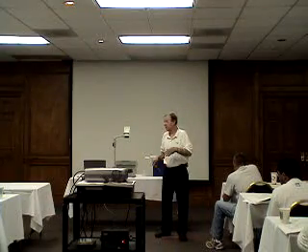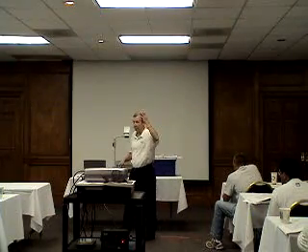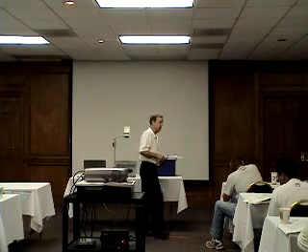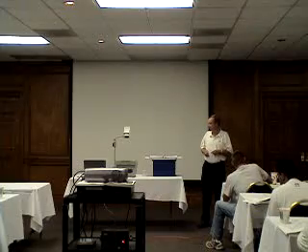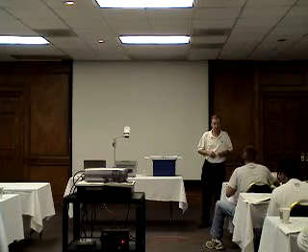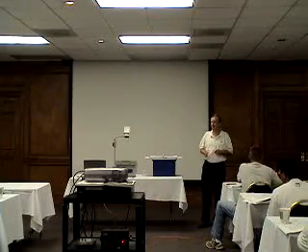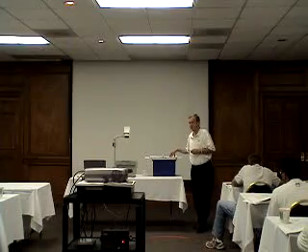And if you know anything about voids, you know those numbers are terrible. That's obviously an unacceptable mix. And I'd say if that's proven to be correct, then the mix is coming up. He is allowed to resample and retest. He is not required to. It is an option of the spec.